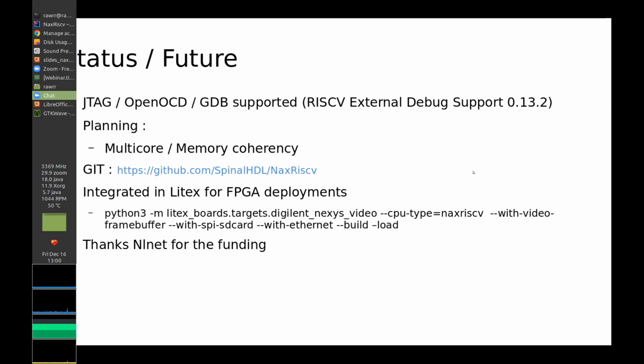Yeah, stageable is more like saying it's really a key to retrieve a concept in the pipeline. Like the program counter along the pipeline could be retrieved using a key, and that key will be the stageable thing. It's really like an identifier which will be used in a hash map to retrieve the hardware signal. So you can use that key in a specific stage to retrieve that signal. And then the pipeline will link all those things together. Like, yeah, the stageable itself will not create logic. You will create logic with the regular SpinalHDL API.